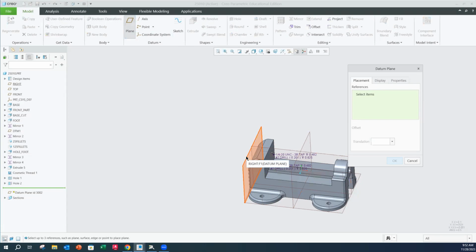Now, the dimension I used for this one was the middle of this. Since the total length was 7¼ overall, because it's 5 inches in between the holes, and then an inch and an eighth to the edge, and an inch and an eighth to the edge, overall it's going to be 7.25. That means that the middle would be half of that dimension.